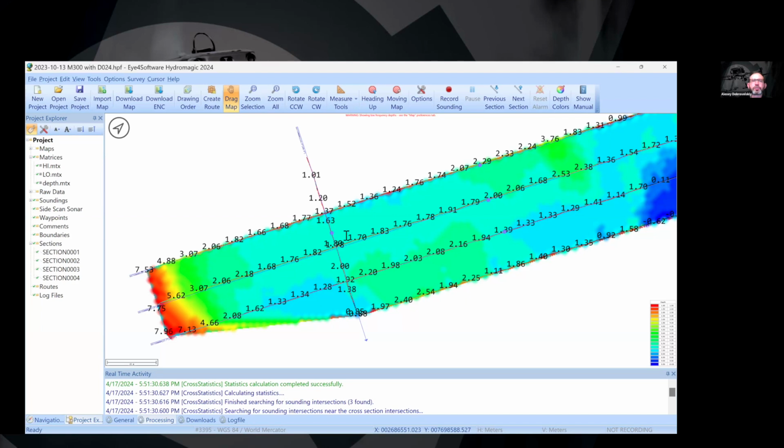Question from Daniel: should the dead zone be added when calculating water body depth data? It is calculated automatically. A dead zone of 15 centimeters means that inside of 15 centimeters, you will not get any measurements. Starting from 15 plus a few millimeters, you will get 15 centimeters plus a few millimeters. So you don't need to do any additional operations to process the data.